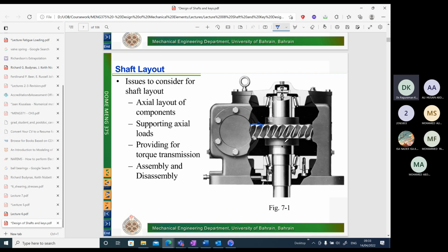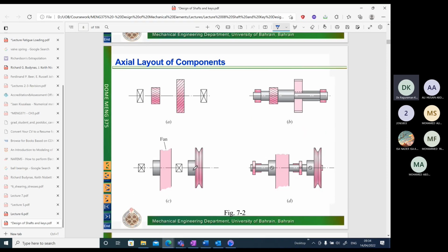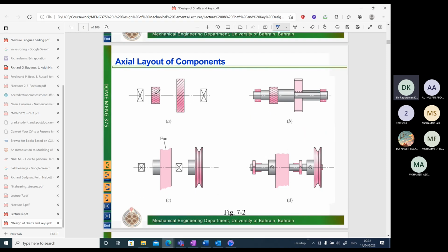And in addition to that, this radial load will cause some bending moment load. In addition, you are providing a torque onto the gears here. Because of the torque, you will also have torsional load. So in a typical arrangement for horizontal shafts, you can see two gears loaded, and this represents the bearing locations. In this particular case, two ball bearings are used in the stepped shaft to position them properly.